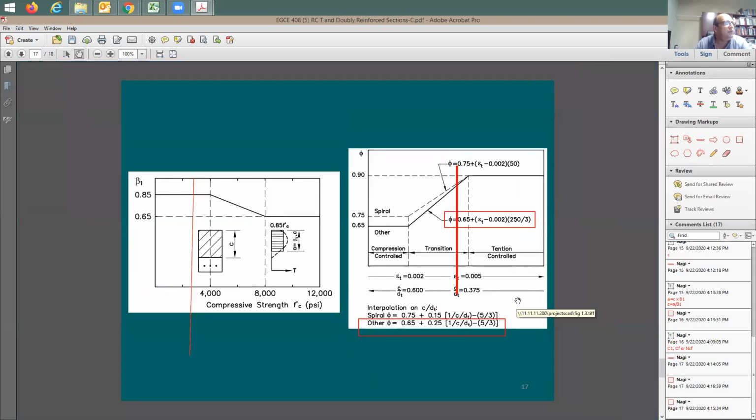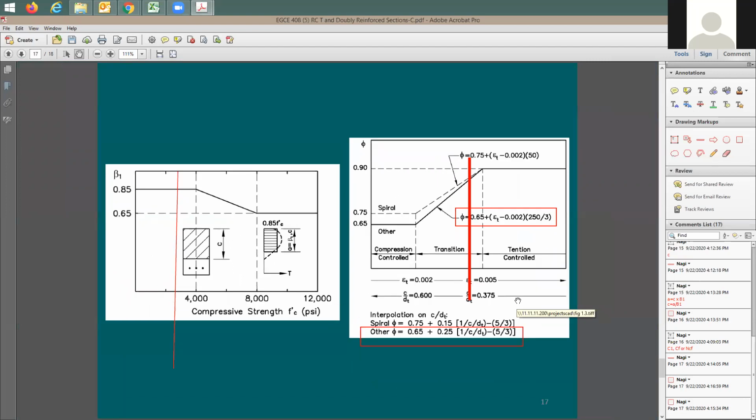All right? Thank you. Professor, I'm assuming that spiral columns are weaker than just a regular solid column. Not really. They are stronger. Oh, really? If you have the same, yeah, because the spiral itself provides more confinement to the concrete. We're going to be talking about this in column design. I'm going to show you the two equations.